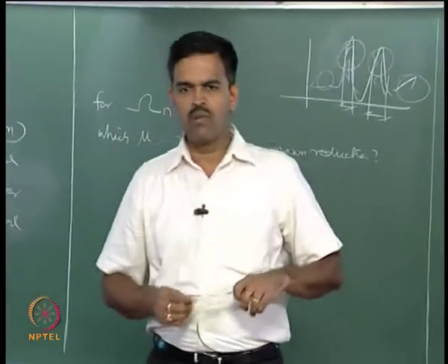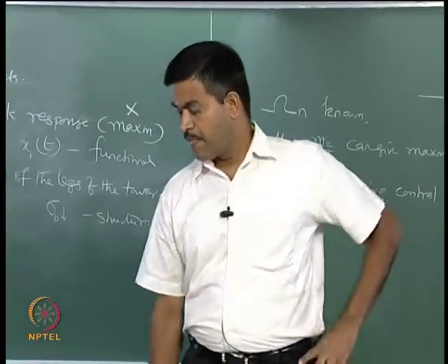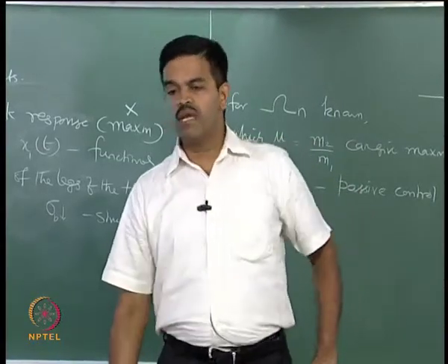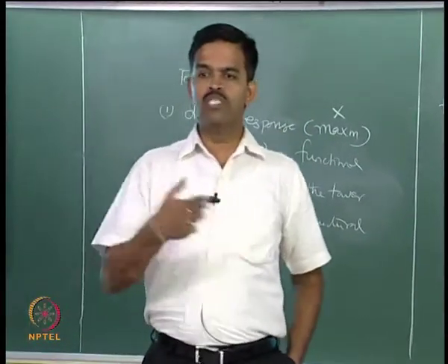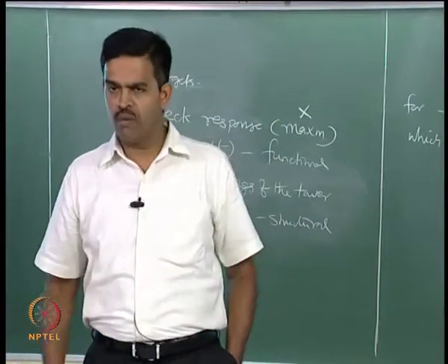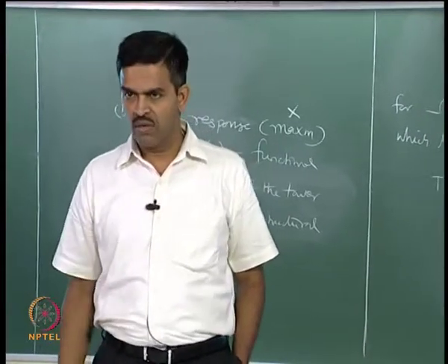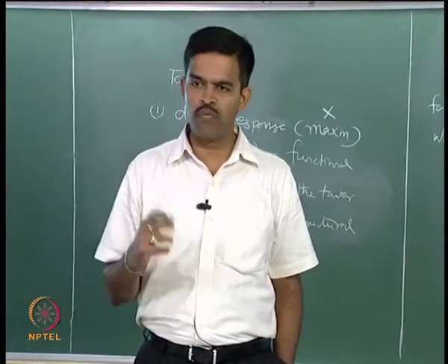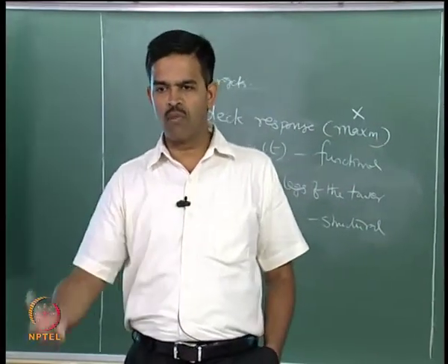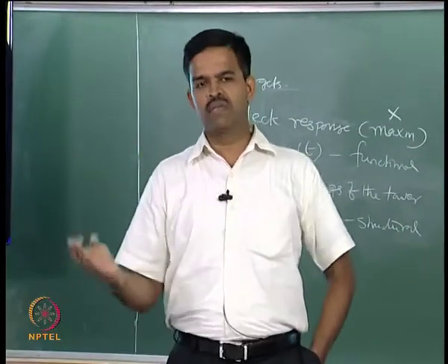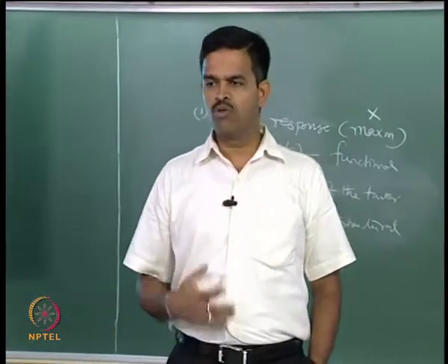In the next class we will talk about the dynamic analysis of TLPs. We will pick up a geometric design of a TLP. We will alter the shape of the TLP from square to a triangular form. We will see what the advantages are and derive the mass, stiffness and damping matrices for a new innovative triangular form of TLP from research papers. We will form the equation of motion, solve it in time domain using Newmark's beta iteration scheme, and then get the results. Then one can also see whether the new geometric form is stable, and how to check the stability.